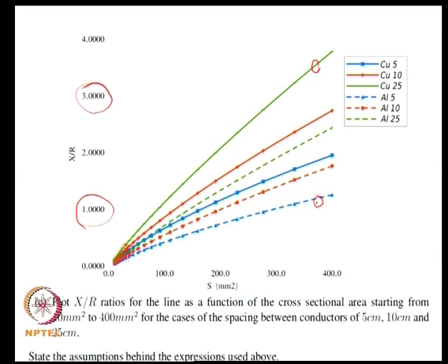We also derived the expression for a single phase system, so 2 conductors. We are also assuming that the current flows uniformly in the cross section of the conductor. Even at 50 hertz, if your cross section is on the larger side, skin effect can be quite a factor and has to be considered. So, we have ignored things like skin effect, and we are assuming uniform current distribution.